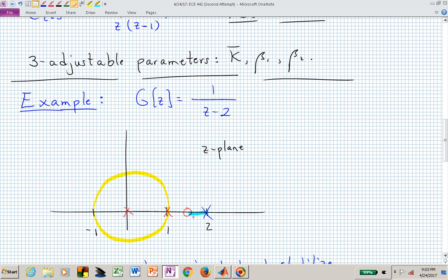And that then means that we probably want to refrain from a 0, one of the betas, between 1 and 2. A more appropriate place might be if we actually, in a sense, canceled this 0 at the origin, then we would be back to the PI controller that we have seen before.